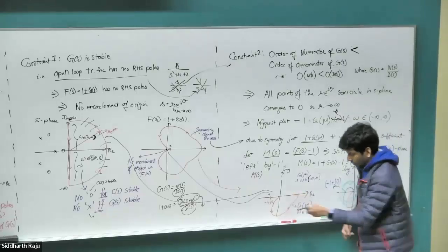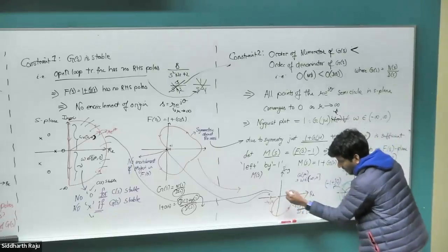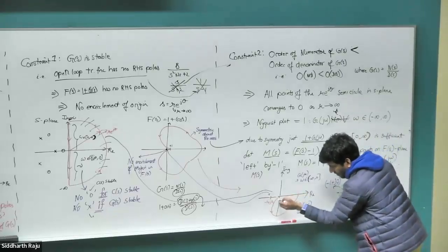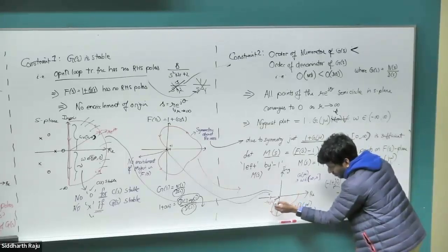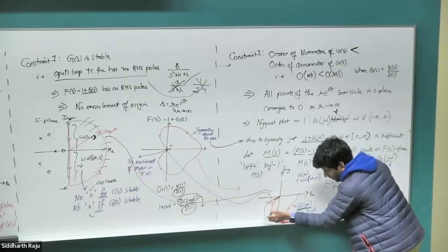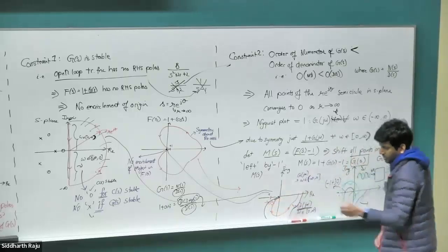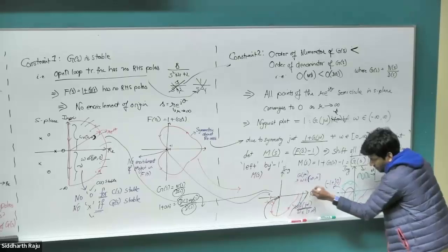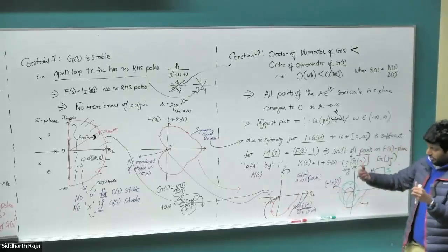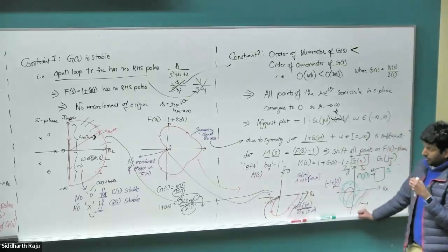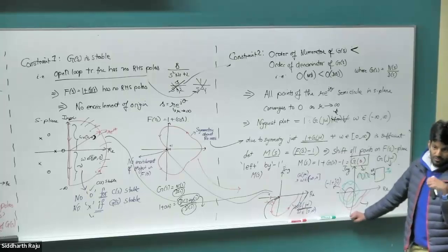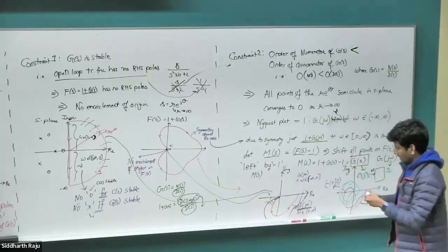The way that would affect this is it would stretch out the signal in some way. Like, you know, all of these points would become double. So whatever this vector is here, that would get double its length. This one would become double its length. So the curve would look like this. Double, sorry. Okay. So it starts to blow up the curve. It could make our system unstable. So if you have a wrong feedback gain, that can certainly make a system unstable.